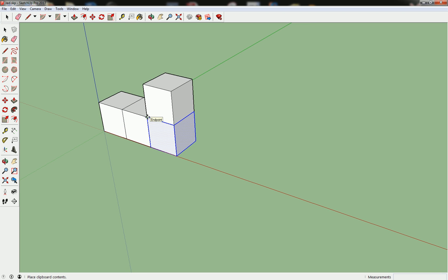At this point, I've got my cubes all set up. You'll need to talk to Mr. Chlebek to see how you can't do a cube that looks something like this and keep it in this shape, because it won't be able to print this surface area underneath this last cube. It can't just extrude a filament. It will fall down onto the ground or onto the heating element table when you're printing. So you'd have to rotate this entire object. Plus we wouldn't have an object that was 4 cubes wide. So I'm going to delete that one.